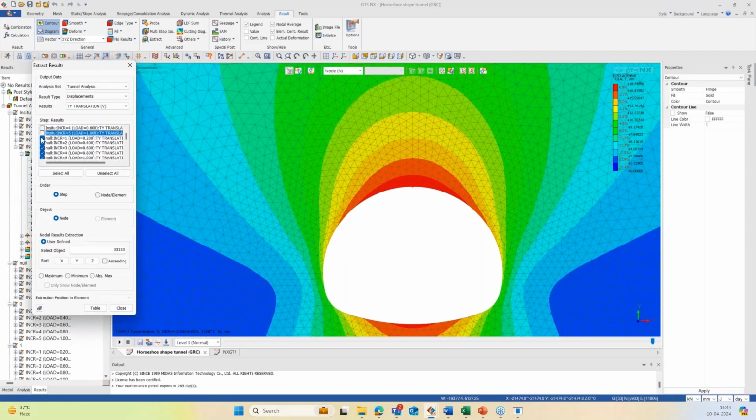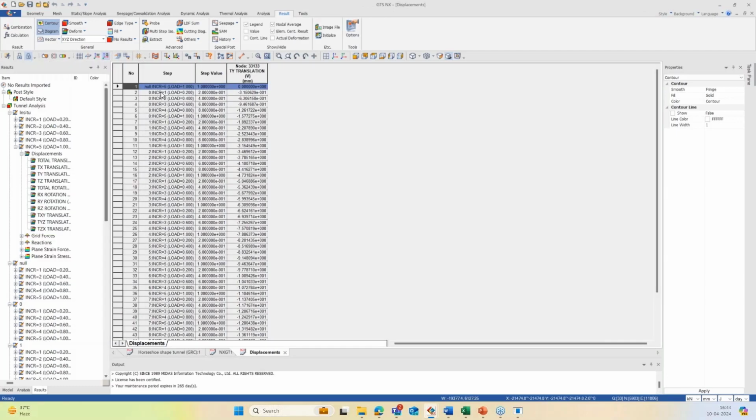Hide these in situ stages and these overburden stages up to 4, because we divide each stage into 5 increments. Now go with the step type and click table. Our table will be generated, which means when there is no excavation, there is zero displacement. At the first excavation increment, it is 10% of 20%, so this is the deformation, from 3 mm up to 20 mm deformation.